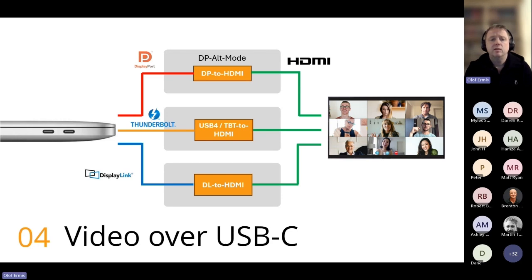Then there is the Thunderbolt protocol, and a bit of a sidestep there. Thunderbolt is a different type of protocol to combine USB and DisplayPort and PCIe, which was invented before USB-C. So it's intended to do the same thing as USB-C, but in a more complicated, yet more flexible manner. Then Intel open sourced Thunderbolt, and in the USB standard, Thunderbolt is USB 4. So USB 4 is not just an extension of USB 3, it's actually the old Thunderbolt protocol.